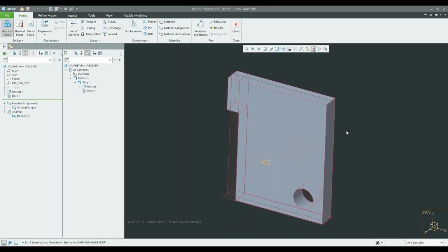What's this material limits? If you're doing any type of advanced failure analysis or fatigue, you would be entering your failure criteria. So you would just populate that information. Specific heat, thermal conductivity for thermal. Composite materials, if you're creating a composite. Miscellaneous information, Y factor, bend tables, so sheet metal properties. Appearance, you might have a specific color. You want to define something specific about it.